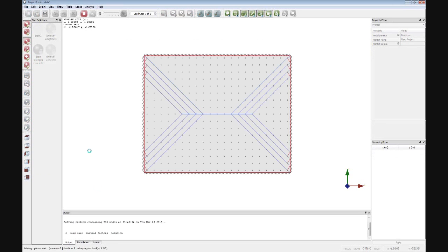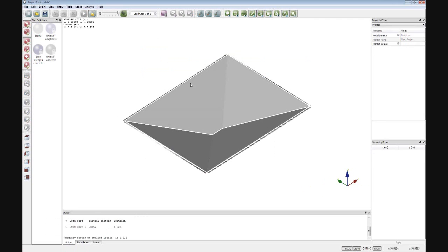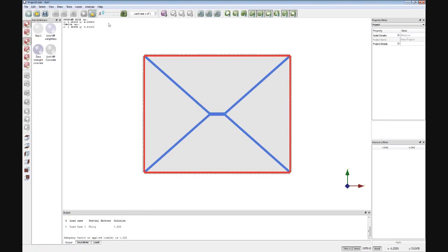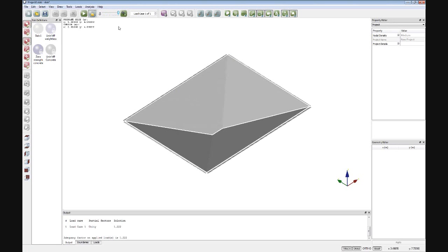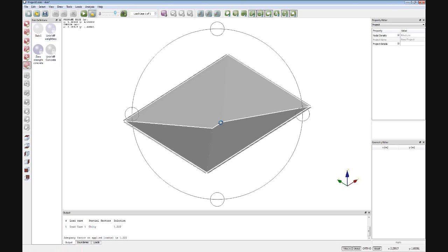And if I click the Solve button, what you can see is it's going through the potential failure mechanisms until it comes to the one which is actually critical, and it's animated quite quickly, so I'll just flick it back to the original, which is showing you that you've got the classical envelope type arrangement of yield lines, and as we saw, if you click the animate button, you can then displace it to see in better detail how the problem is actually behaving at the point of failure.